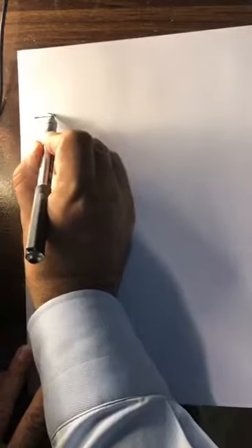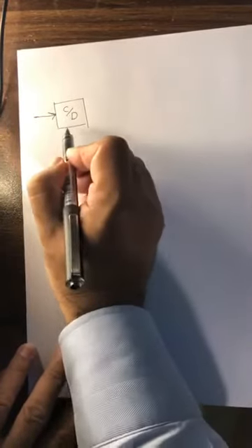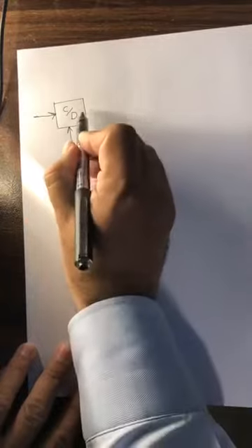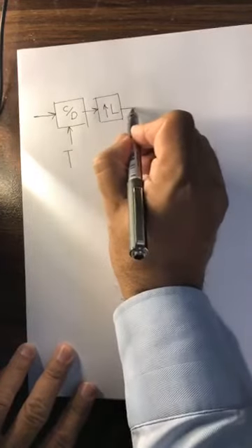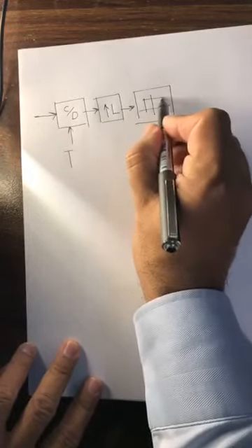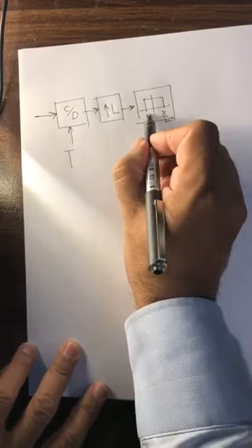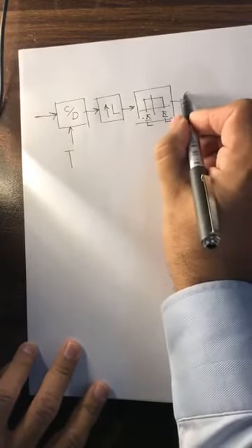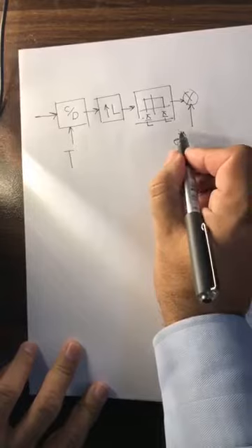Okay, so an interesting question where you have a continuous to discrete time converter, then inserting of zeros, then passing of this through a pi over L filter, then shifting the spectrum of the signal by multiplying by e to the j pi n.